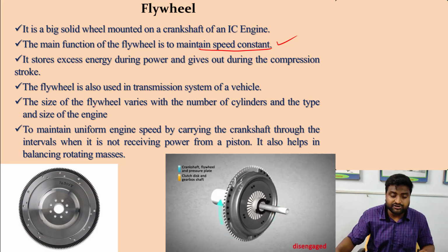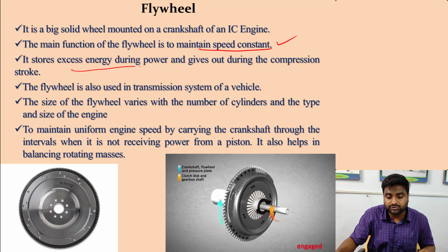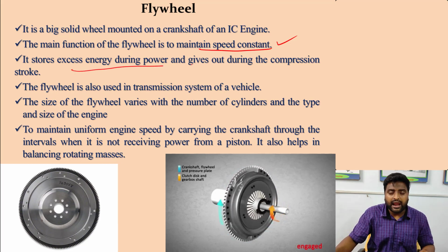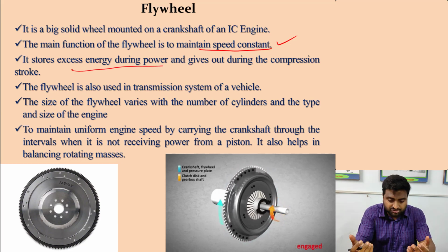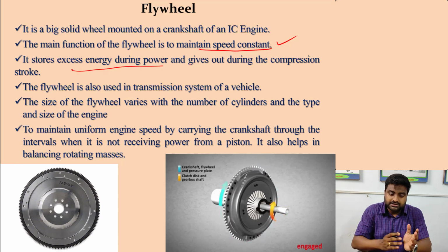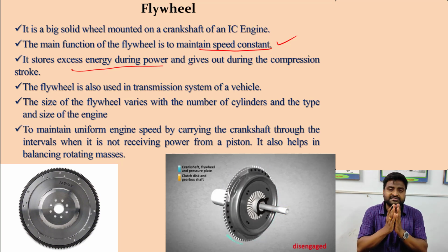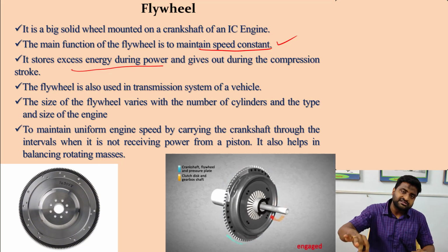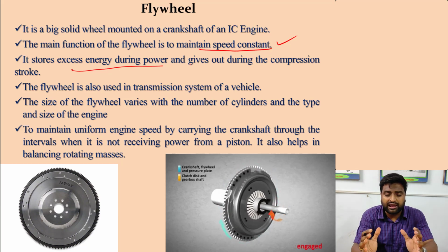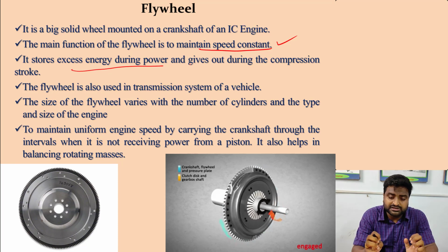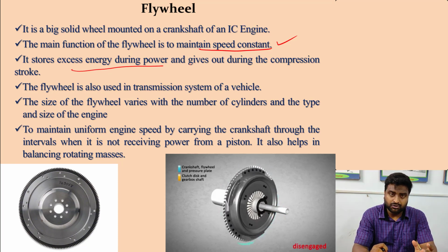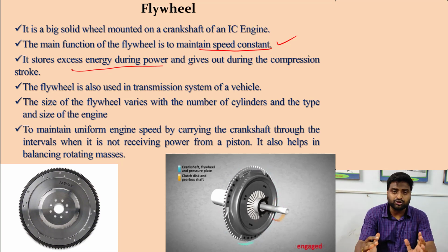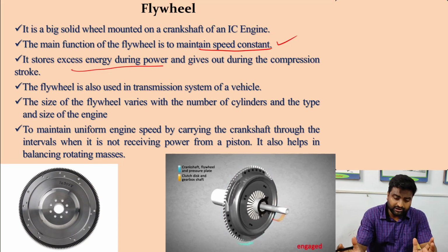Another function is that it also stores excess energy during the power stroke and gives it out during the other strokes. I will tell you later how this is done. But you can say that the excess energy is stored during the power stroke and released during the other strokes. So the flywheel helps to store the energy, maintain the constant speed, and the size of the engine depends on the flywheel.